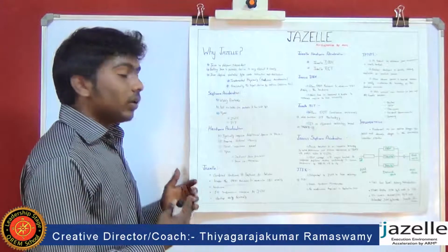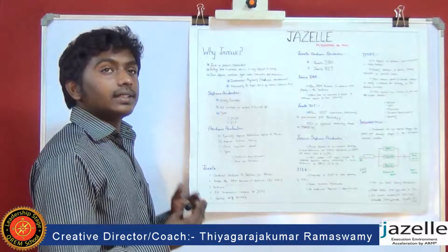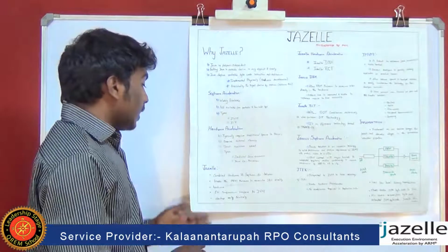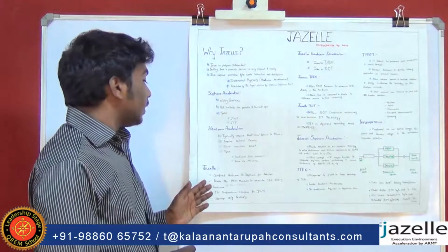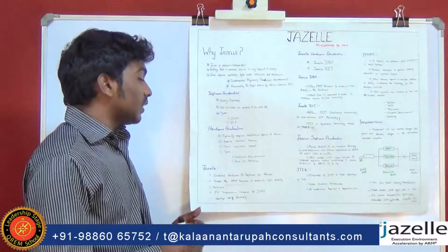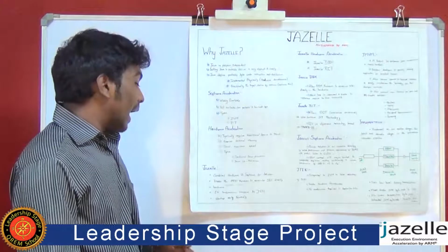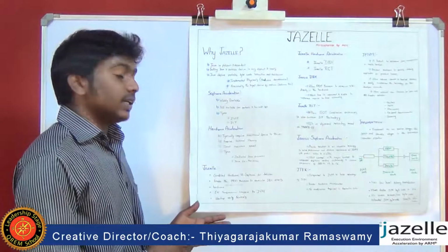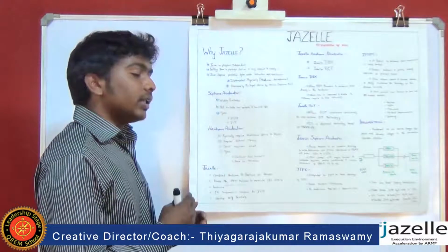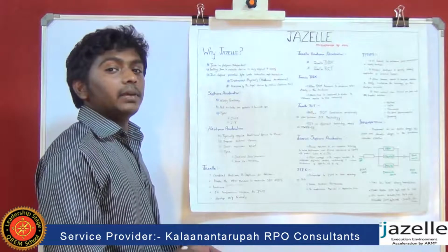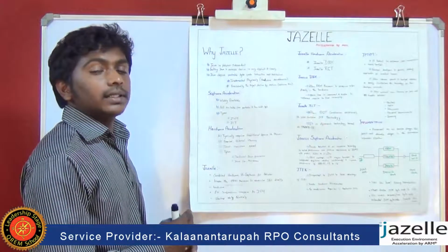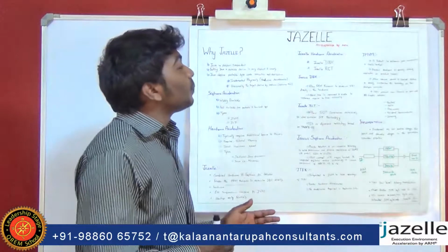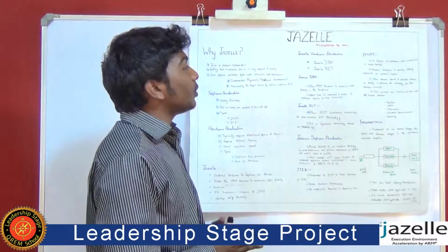For this, we go for Jazelle, which is a combination of hardware and software used for Java acceleration. In Jazelle, the ARM processor executes the Java byte code directly within the processor. This is used for a multitasking Java virtual machine, and the performance compared to JVM is increased by 80%. The starting time is also improved, and Jazelle is divided into two types.